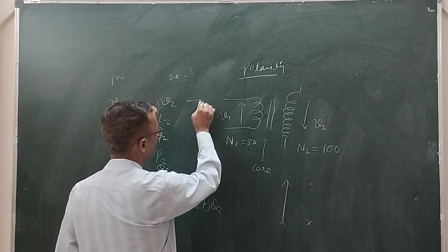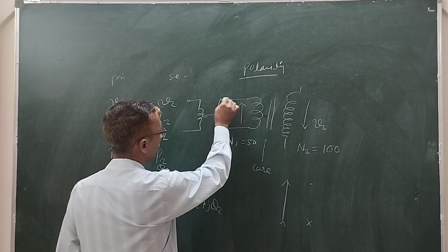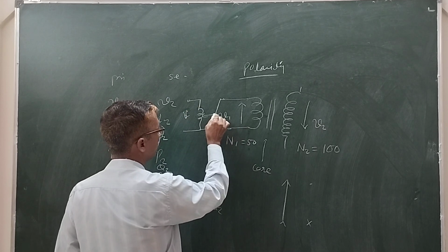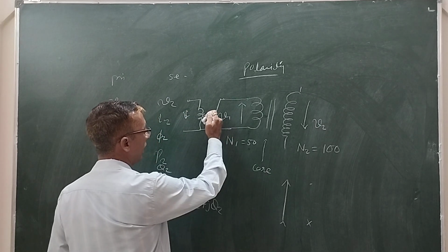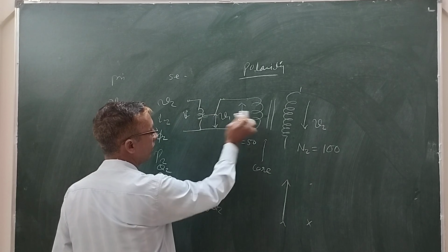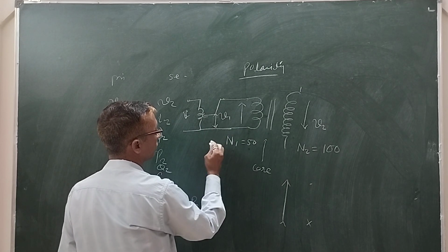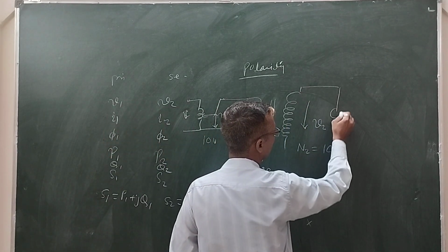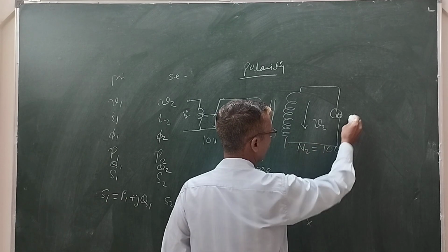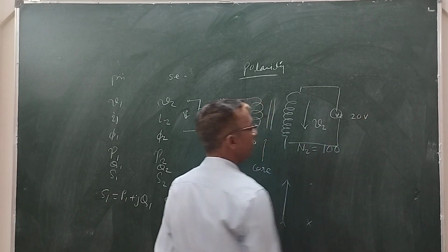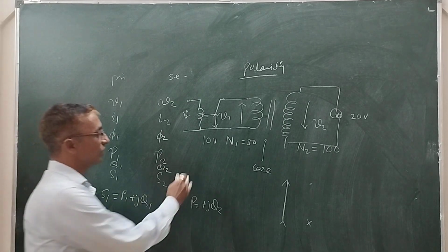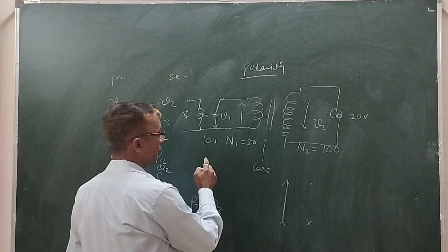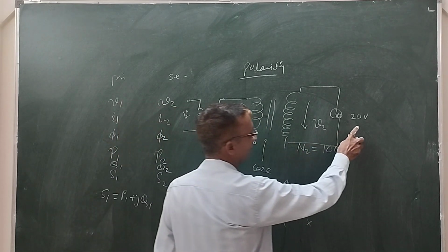Let us try to draw something, an auto transformer here. I am applying voltage V on this supply side, and here it is V1. Now suppose I make the voltage applied to the winding 0 at this point, and I will just increase the voltage. If I give a test voltage of 10 volts here, I will measure on this side what the voltage V2 is. Suppose I am getting 20 volts here. Then it is called a step-up transformer, because the voltage has been increased from 10 volts to 20 volts. It means I can say that this is the high voltage winding.